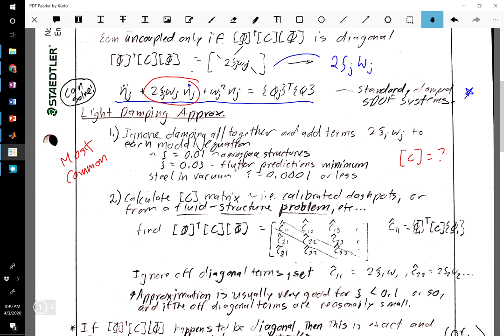Another interesting tidbit: every material has some amount of damping, and sometimes you can look that up in tables. For example, a steel bar, if we put it in vacuum so that there's no extra damping from the air carrying away energy or anything else, they've measured that the damping ratio tends to be on the order of 1/100th of a percent, or 1/10,000th.